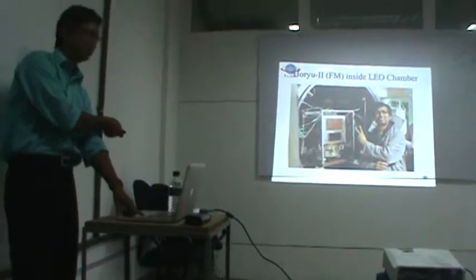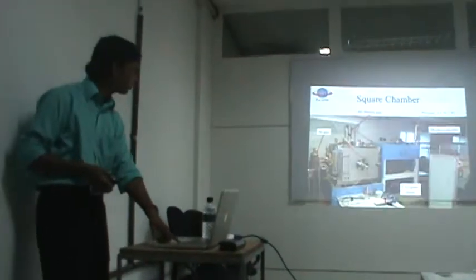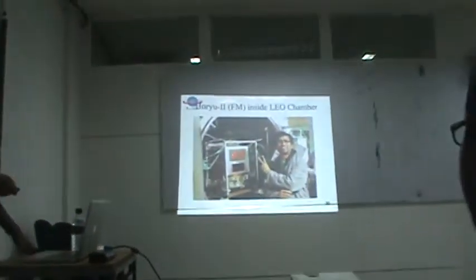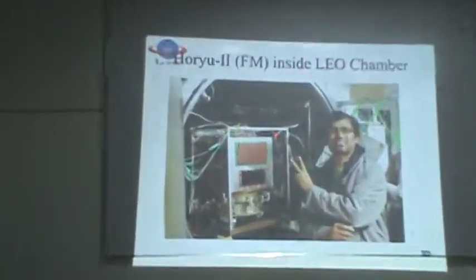And I have some other talks on this satellite. Why are there so many cables? Because we are testing the satellite. We attach here many thermocouples. You know thermocouple to measure the temperature. Okay, and here it will be in hot cycle and cold cycle. On hot cycle and cold cycle, we run the satellite, power switch on, and we check whether it's running or not. That is our objective.